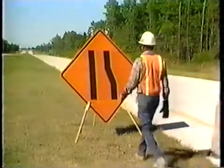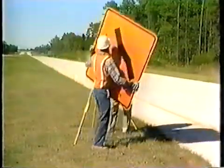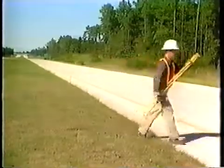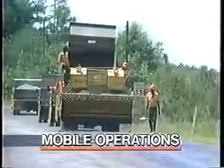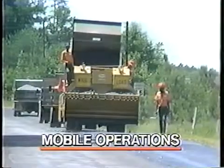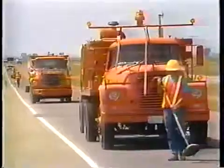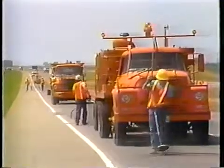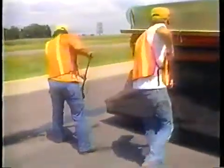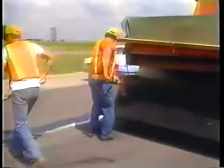After the project is completed and all workers, materials, and equipment are off the roadway, the traffic control devices are removed in reverse order of installation. Finally, let's look at mobile operations. Generally, this work uses a moving vehicle train with occasional stops of less than 15 minutes. Mobile operations should be used only during daylight hours and at locations that offer good visibility.